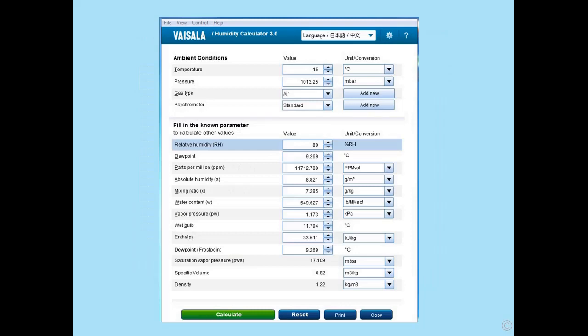However, psychrometric charts are great. What they're brilliant at doing, when you're learning, is to have a look at the relationships between temperature, humidity and dew point. One can look at these as two-dimensional charts. However, an easier way to do it is to download one of these calculators to your computer or your telephone. Put in the temperature, put in the relative humidity, and then we get lots of other readings, including vapour pressure, as we can see halfway down in kilopascals for those particular conditions.